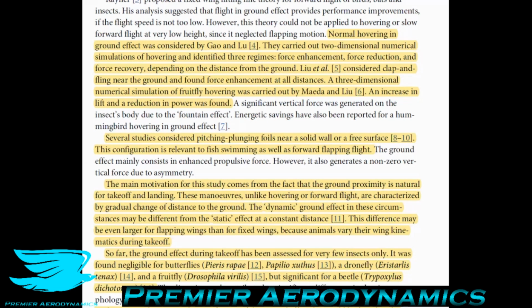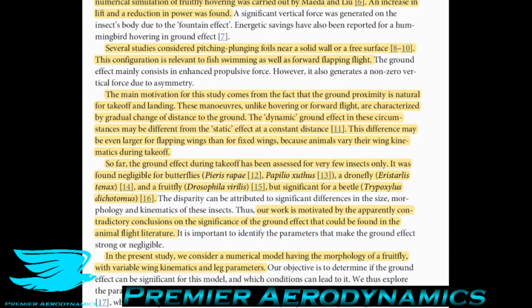They have a similar kinematics and they can experience similar effects. So the main motivation for this study comes from the fact that the ground proximity is natural for takeoff and landing. These maneuvers, unlike hovering or forward flight, are characterized by gradual change of distance to the ground. The dynamic ground effect in these circumstances may be different from the static effect at constant distances.